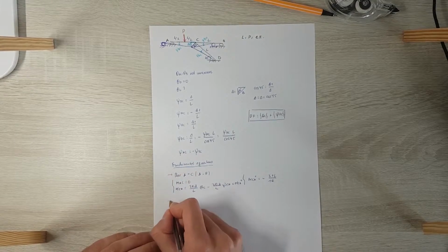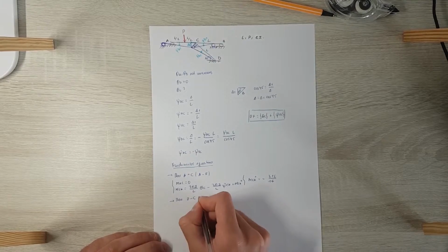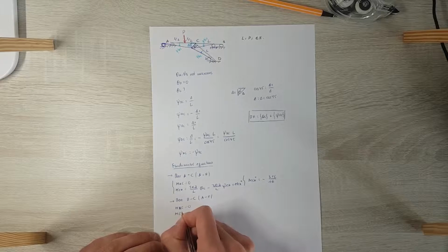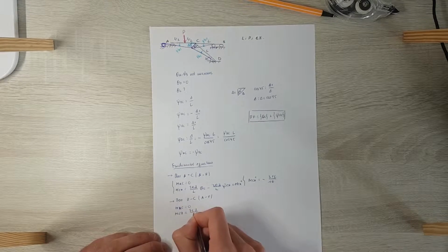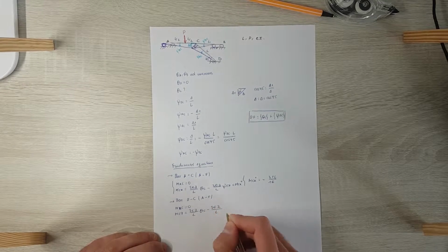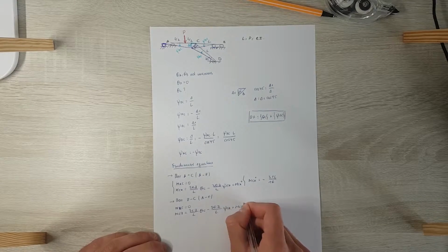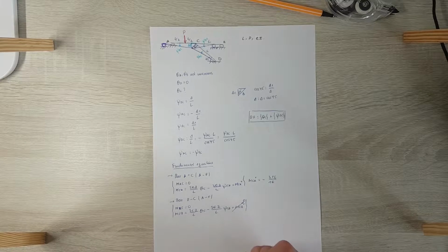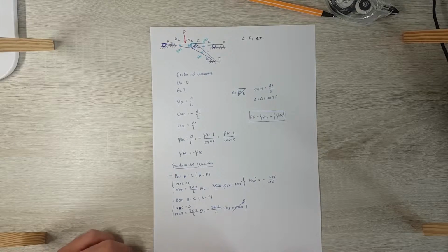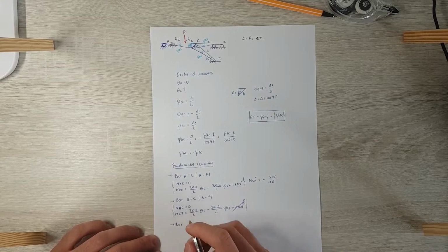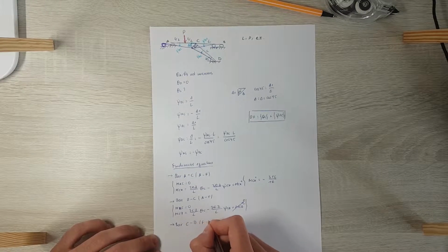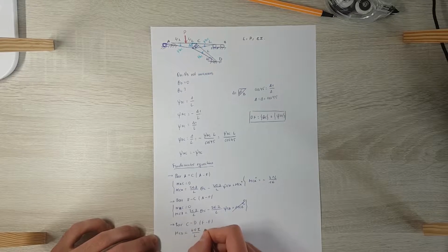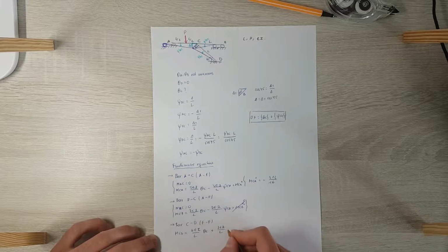So now the bar BC, which is articulated fixed too, so MBC will be 0 and MCB will be given by the same equation as before. In this case the fixed-end moment is 0 because we have no external loads or thermal loads. And finally the bar CD, which is double fixed. So in this case the equation changes and is given by this formula.